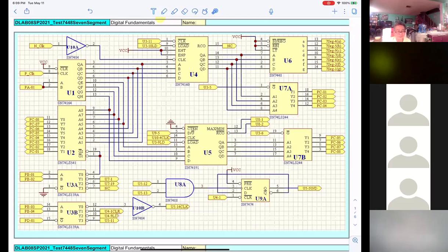Now, after it's done counting up, that means U5 generates the pulse coming out to plug into U9. Now it will toggle. It was 0, now it goes to 1. And then once it counts down to 0, then what happens? You count down, try again. It does the same thing. It will be automatic. So it just keeps counting up and down, up and down. Exactly. Okay.